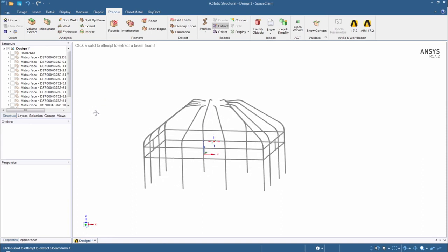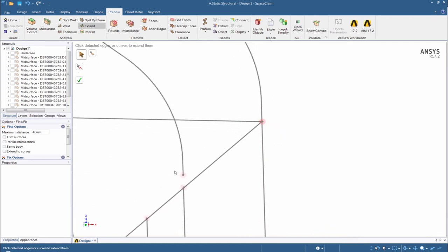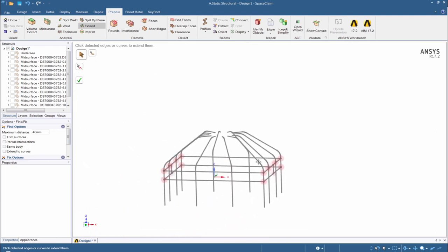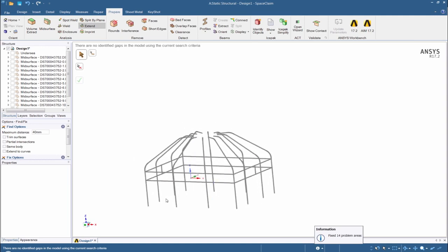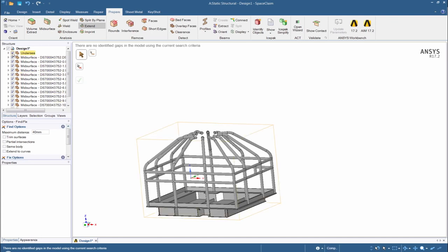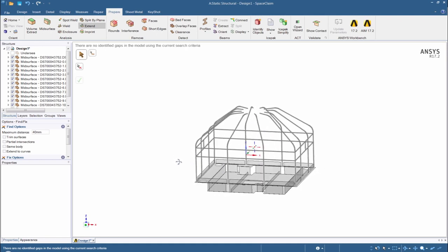And it does. Now, I know we started with kind of dirty CAD geometry, so I want to run this extend tool that's going to go look for anywhere where maybe things didn't close up properly, or maybe there was some overages like this, for example. That's not good, or these gaps that were left. SpaceClaim's great at finding those and just eliminating them for you and letting you know, hey, this was a problem I think you should fix, and we do. So we're in good shape now. So next up, what I want to do is let's bring back everything, show all, and we can just click this button to get rid of the original tube structure and solid structures that we've already eliminated and just be left with our beams and shells.